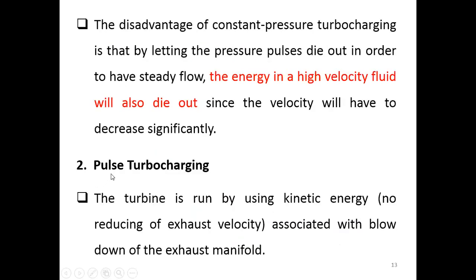But for pulse turbocharging, the concept is that we accept the pulse, but we just want to minimize it so it does not affect our turbine much. The reason we have to accept the pulse is that we want to keep the kinetic energy in our exhaust flow alive. We don't want to kill off the exhaust kinetic energy.